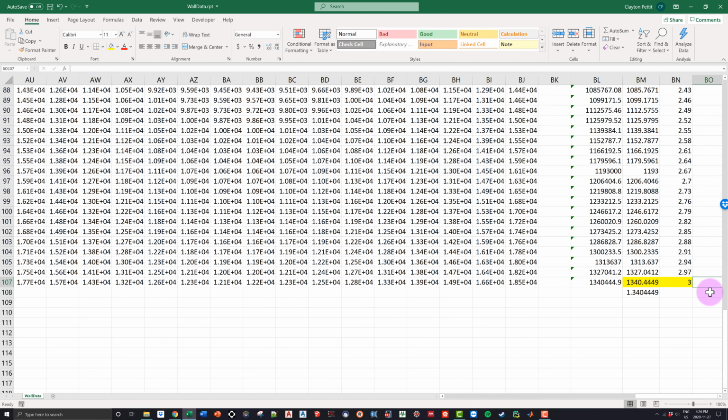All right, so when you are doing your reports, for each one of those wall openings, I want to see two things. One of them is the von Mises stress plot, and I want you to tell me if it actually fails due to the stress limit. The next thing I want you to do is tell me how much load it takes to displace the wall by 3 millimeters. And once we have that, I want you to tell me the factor of safety. All you have to do is take your total load and divide it by 1,000.